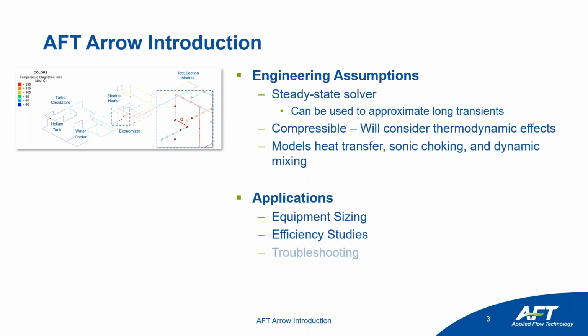Some common applications. Today we'll look at equipment sizing for an orifice, but you could also size things like compressors or blowers, control valves, relief valves. Again, anything tangential to that piping and hydraulic analysis. As energy efficiency becomes a higher and higher priority for many different companies and for systems, what opportunities can you assess within your model to tweak operation to improve operating efficiency? In the same vein, if you have a physical system that's running into problems, you could build a model and that would indicate any differences, helping in the troubleshooting process. Or if you have a physical system and you're trying to increase throughput or add a new consumer, you can test that out in the software, identifying where you need to make modifications or if the existing system can handle that new capacity.